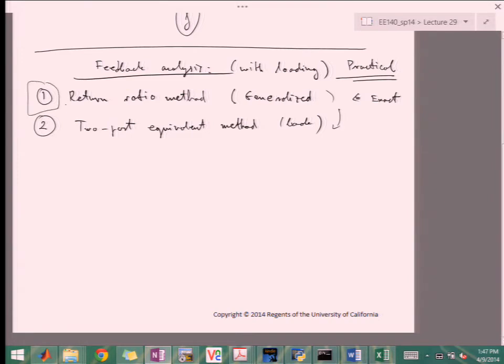method. And then in some cases, you could apply Miller's theorem to solve the issues, and there are some other approximate methods. But Miller's theorem, as we know, only works when gain is high. So when we do frequency analysis beyond the poles, it loses its applicability.